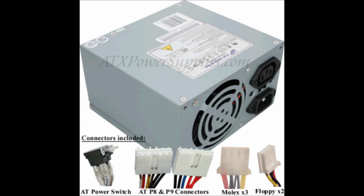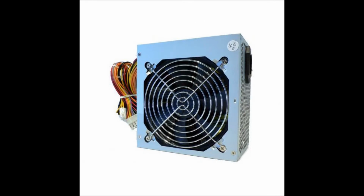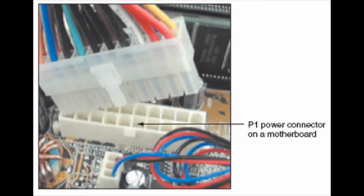Older power supplies had power cables that provided either 5 or 12 volts of DC. The newer power supplies provide 3.3, 5, or 12 volts of DC. In addition to providing power for the computer, the power supply runs the fan directly from the electrical output voltage to help cool the inside of the computer case. Temperatures over 185 degrees Fahrenheit or 85 degrees Celsius can cause components to fail. And when a computer is running, this and other fans inside the case and the spinning of the hard drive are the primary noisemakers of the machine.